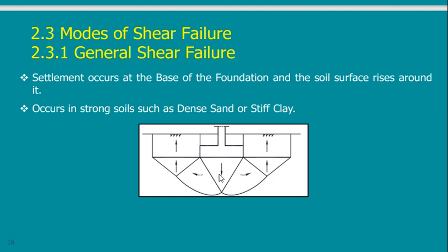What I'm going to speak about now is called the general shear failure. General shear failure means that I'm pushing this, and as we said, each area is a block. The area is not going to be compressed. It will act as a very stiff block. So this triangle is a block. This wedge and the other one all around is another block.